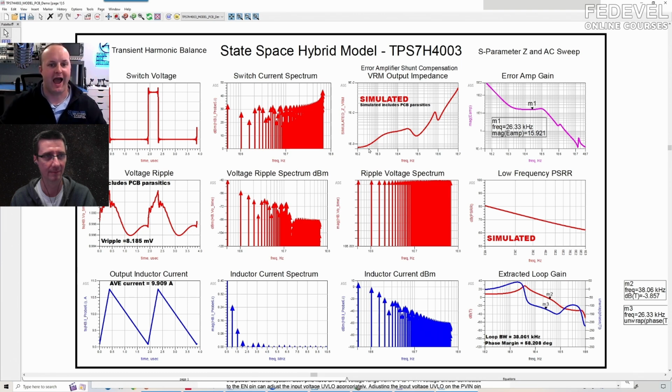Now we have the impedance. Oh, hey, wait a minute. We have the output impedance right here of our PDN with our V out. By adding in those board effects, here's my VRM. This is the control loop of my VRM, and this is the output inductance of the VRM's control loop. I can see this is a bulk cap here. I go up and I see, what's that? Right there at 1 megahertz. Didn't we say this is like a 1 megahertz period? Around 2 microseconds to just after is about 1 microsecond, so it's a 1 megahertz period. This looks like the smoking gun. There's a resonance right there at 1 megahertz. Well, how do I figure out what that is?